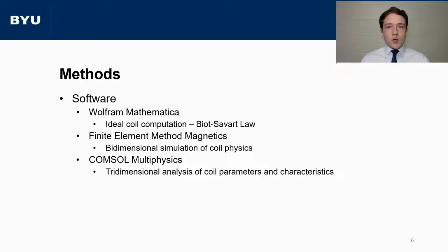Knowing that the maximum gradient possible in the longitudinal direction would be generated by a single turn coil of infinitesimal wire diameter, we started to investigate ways of making a design that would approximate that expectation while conforming to our other constraints. By analytical and numeric simulations using software such as COMSOL Multiphysics, FEM, and Wolfram's Mathematica, we found that a 36-turn single coil of outer diameter 40 mm, inner diameter 20 mm would match our gradient requirements for this design.